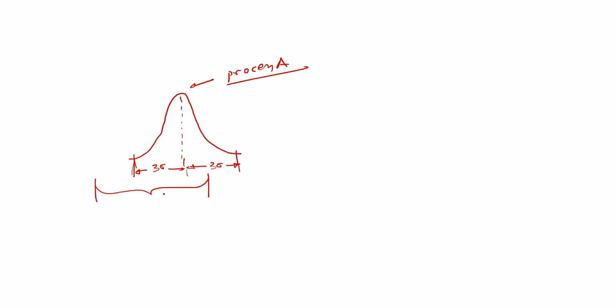Now in that case, you cannot use the Cp value immediately, because for the point of discussion, consider the tolerance value is equal to 6 sigma value. With the previous indication of Cp value, we get Cp equal to 1 in this case, because tolerance is equal to process deviation. That will give the indication that 99.73% of the parts will be accepted.